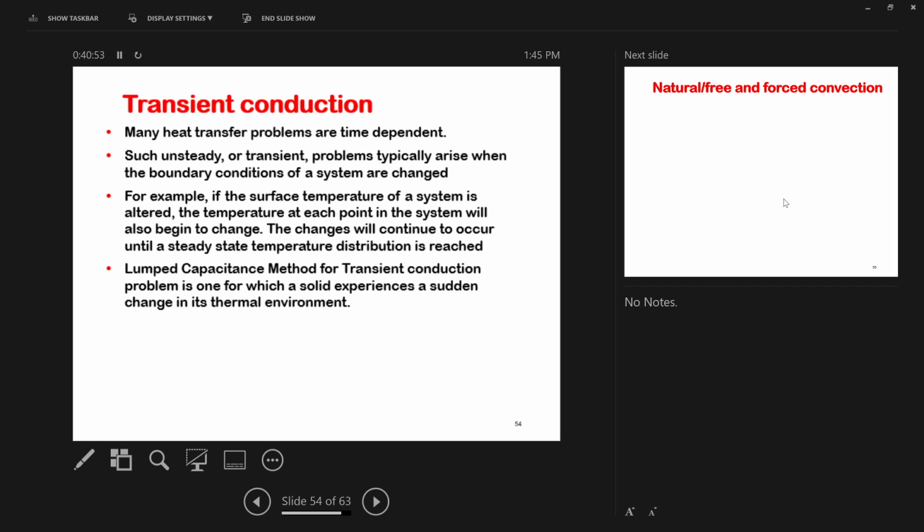Convection, exactly. So we have both of them, right? And it is a transient case. So this is a very complex system to analyze. But the lump capacitance method tries to simplify this type of system. The lump capacitance method assumes that conduction is happening so fast that the temperature inside this solid ball is not at Ts, but is always changing and always uniform, right?